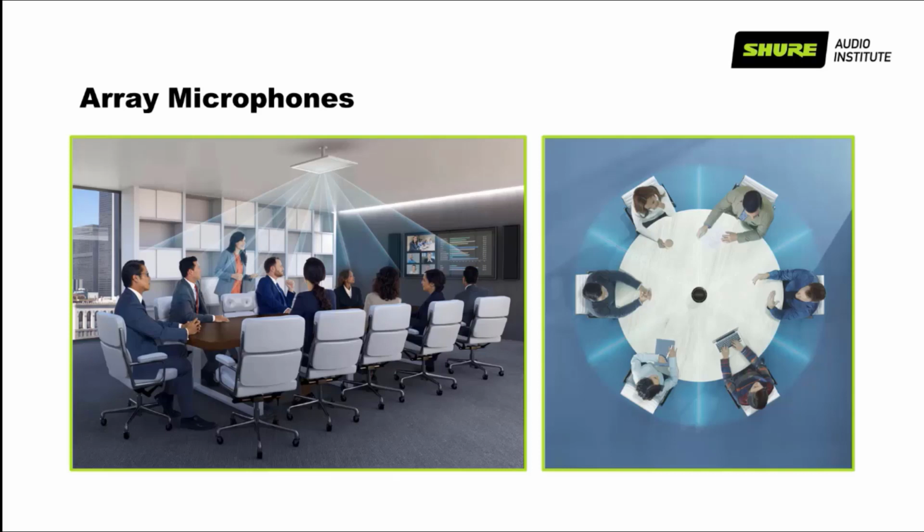And again, that's all done electronically, but that allows some array microphones, like pictured on the left here, to have a distance factor of as much as 4, right? So if you want to really get into putting a microphone further away, which of course happens if you put a microphone in the ceiling, the further away the mic is, the more important that high directionality becomes. And that's another advantage of the array microphone: in addition to being able to move the patterns around, you can create this really highly directional pattern.